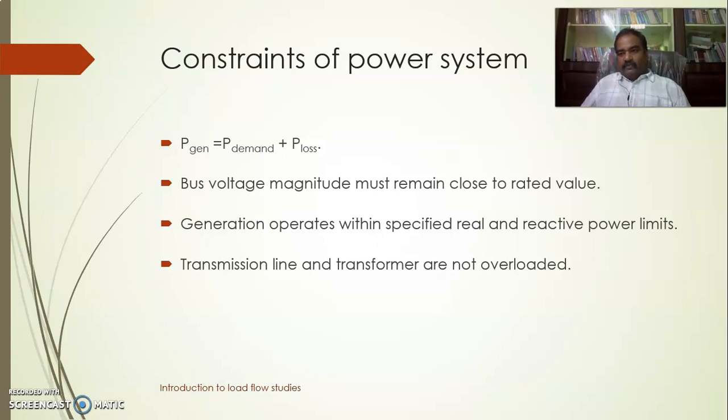If you generate more power and you don't have any storage capacity, then it will lead to a catastrophe. The generator frequency might increase, and we experience non-synchronism of the synchronous machines, which may ultimately lead to collapse of the power system. So that's why the biggest constraint is always about the power which is being generated in the system and how much power is being transmitted and delivered to the consumers.